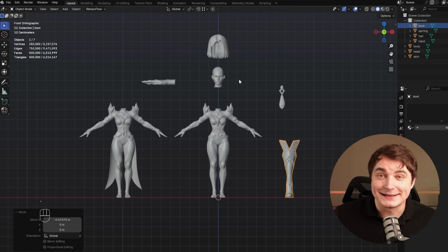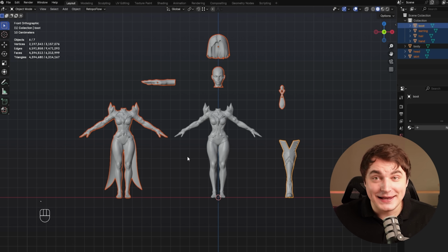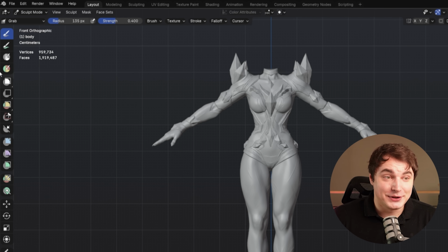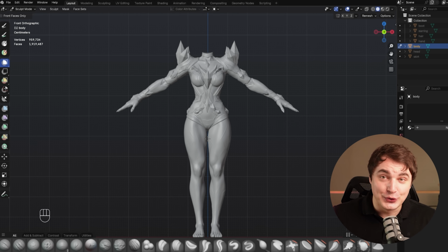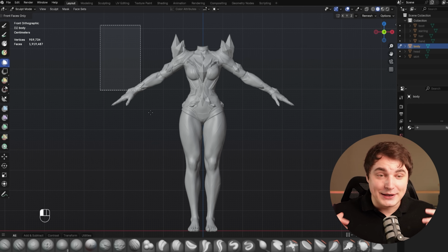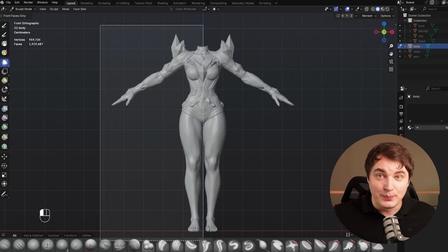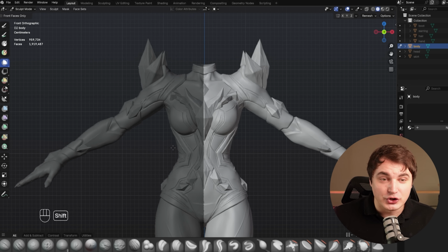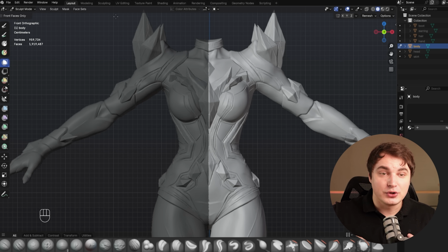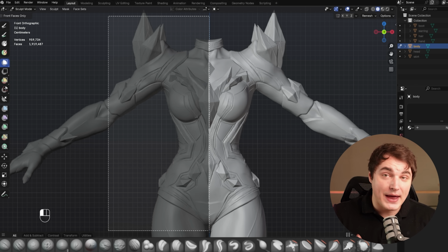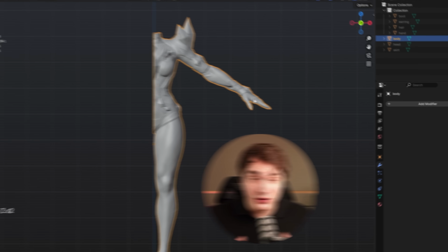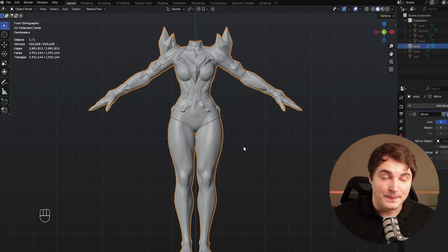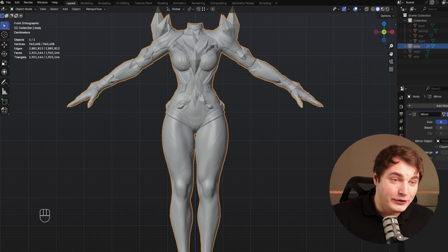I would compare this step with the classical sculpting step, and since we're gonna work with high poly meshes, we're gonna use sculpting tools. So the whole thing that we need to do here is to combine all parts into one body, make sure that the proportions are right. We can actually drop the original reference here, adjust the proportions. With sculpting tools, we can also go over geometry, smooth some stuff, add some extra details if needed. Also for symmetric characters, I recommend to do mirroring, which I actually did for the body. That will save you time on texturing, on low poly, etc.